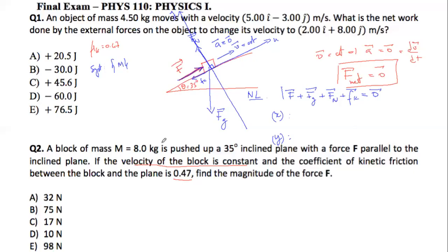So I project along x. The force along x is just plus F. You project this along the inclined plane, plus F. Gravitational force along x, the angle theta is coming here. So this is what I need. And again, as usual, it's minus mg sine theta.